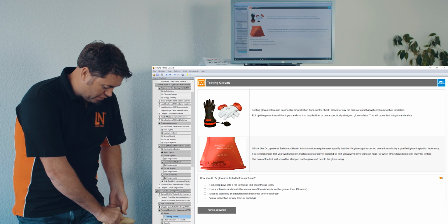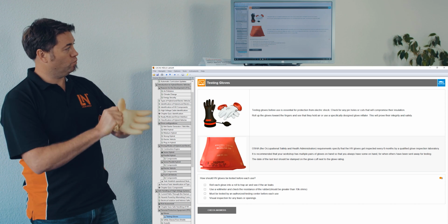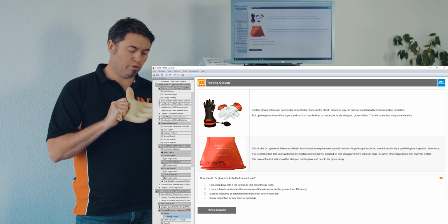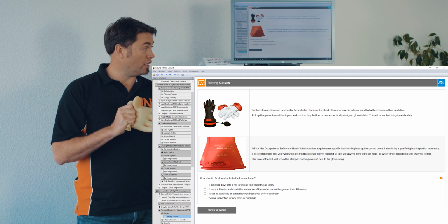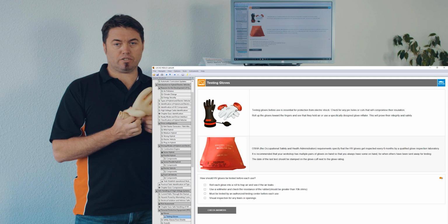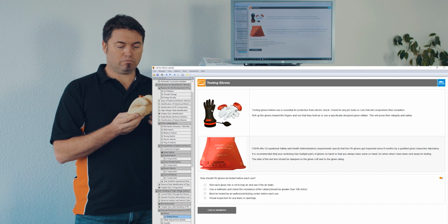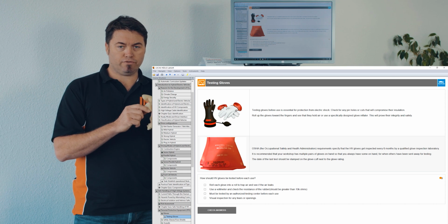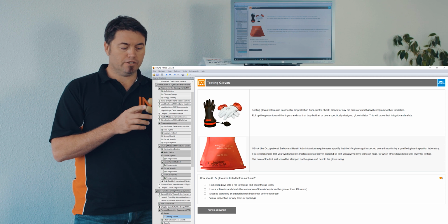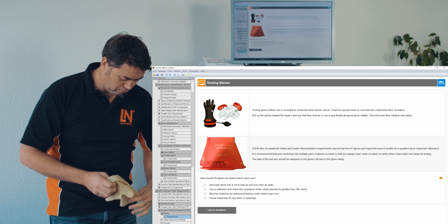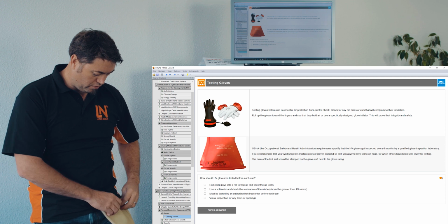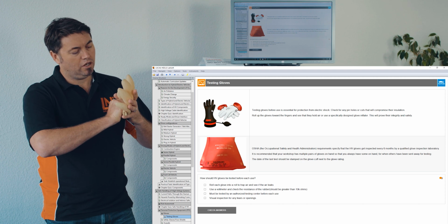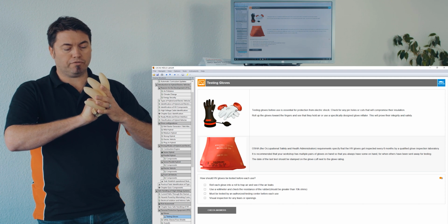What I've found, however, is that we've done some testing with the pump type of system. We put a little pinprick into this type of glove under pressure, and it takes a good 5 minutes before you see the glove go down. Depending on the size, a pin has gone through the glove, a very small hole. So it's not just a matter of checking, holding for 2 seconds or something. You really need to hold on to it for a little while and make sure that those gloves are okay.